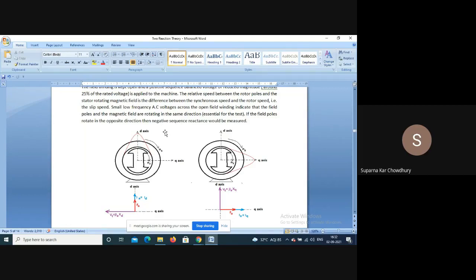As it is a magnetizing current, the requirement will depend on the reluctance of the magnetic flux path. Now we have applied a constant voltage, frequency is also constant, so the flux should remain substantially constant. When the MMF is coincident with the direct axis, a small reluctance is offered by the small air gap along the direct axis.